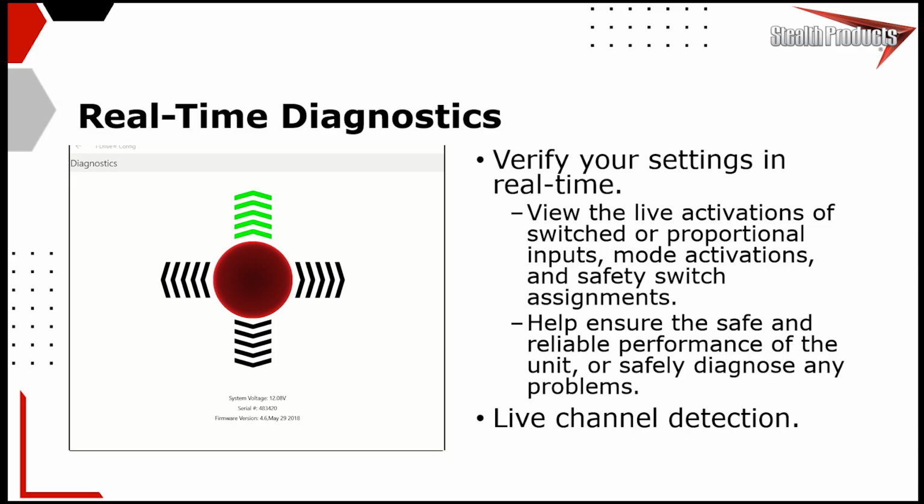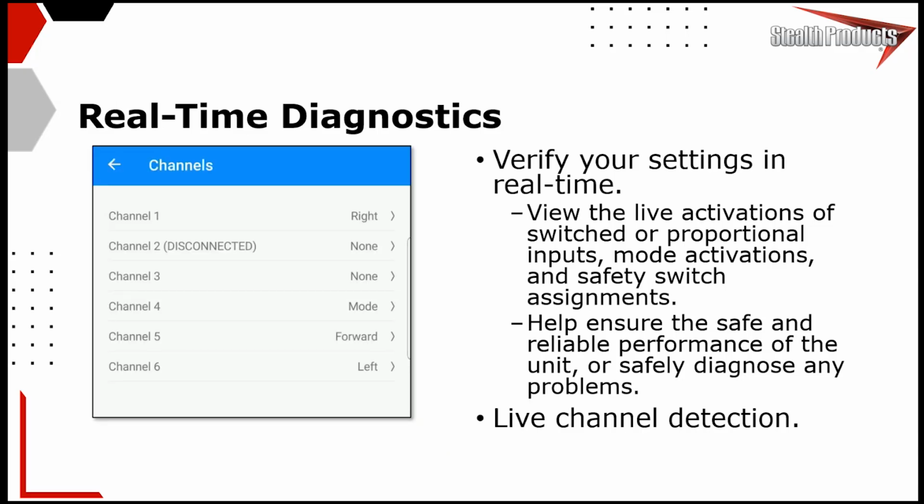We are able to also use this screen here to identify which channels or ports on the iDrive interface don't physically have something plugged in. So let's say I'm having a problem turning left, right? I can look at my app, I can check this screen here to see the channels in this menu, to see if iDrive even recognizes that something is connected, right?